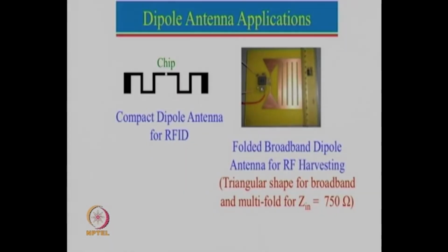In fact, it all depends upon where and how you need to fit the RFID antenna. So you can go like this here, or you can go straight like this, then come back here, then go over here, maybe bend like this, and you can make it as small as possible, or you can use a circular waveform also like this here. You can make it in an elliptical shape, or the idea is that it can fit in. Suppose you want to put this RFID on a circular shape. Then we can put the chip in the center here, and then we can go around. We can go like this here, like this here, the other one can go around. You can make whatever shape you want to do.